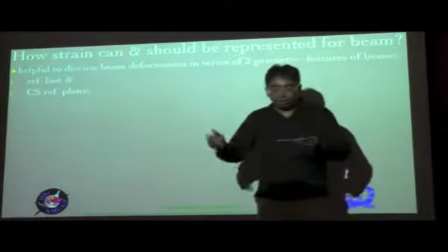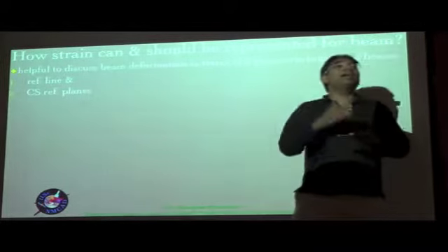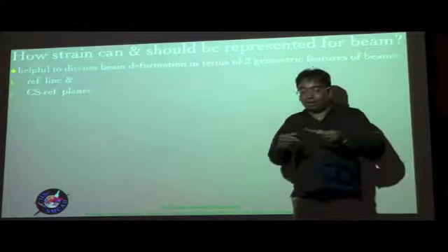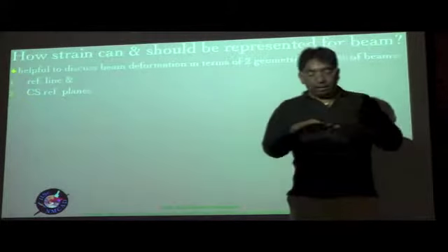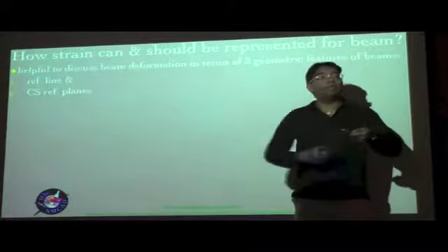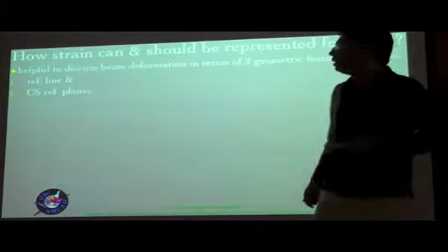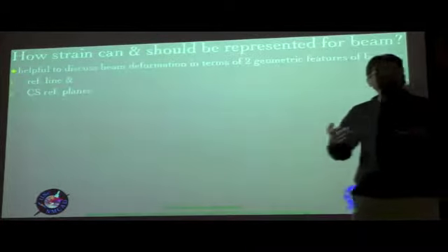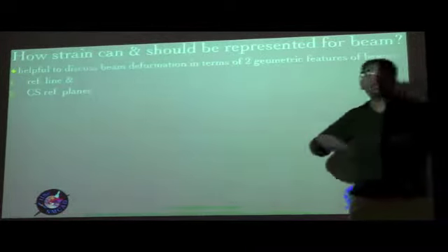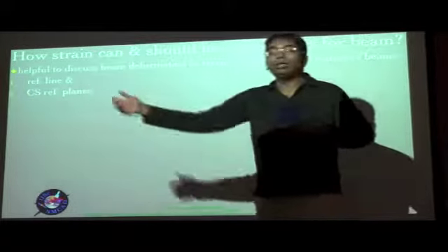Even if it has different cross-sections throughout, it can so happen that they are of the same class. For example, it could be an I-beam, but it might have different flange lengths along the span, typically causing a taper in the wing, for example. But even in such situations, we can use the same results but with different numerical values for the flange width, for example, along the length.